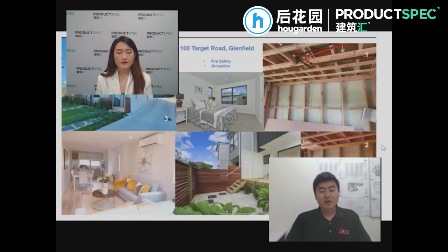The sequence is simply they started building one side of the wall first of all, which is the timber framing. Once that stood up, they started to install the Integra panels with the mortar system. Layer by layer, they install the Integra panels, and after that, they finish with the second part of the wall. So the wall that you're looking at right now only took 2 people no more than half a day to install. The panel itself is quite lightweight, weighing about 35 kg. So when you transport it, between 1 or 2 people, we recommend 2 people can install the system.